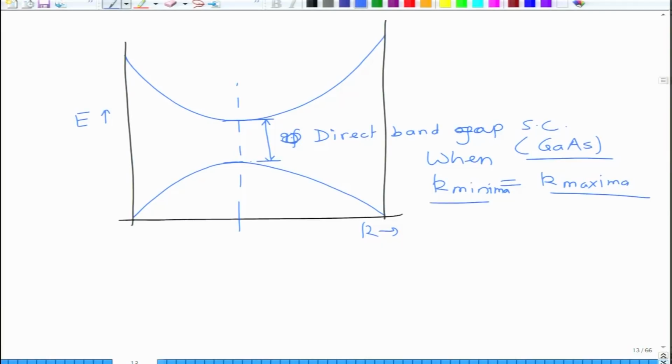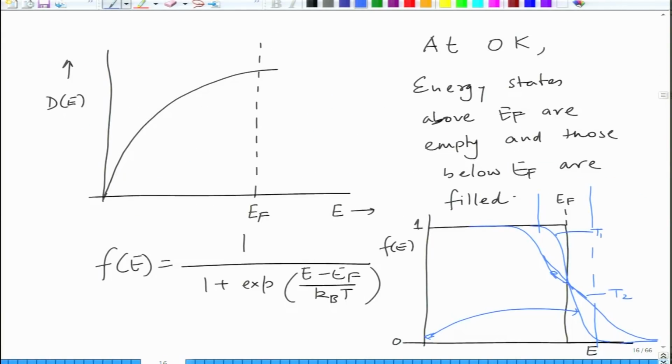Essentially, that is what we are saying in Fermi-Dirac statistics, that there is a reference energy Ef below which all the energy levels are filled. So, this valence band may be up to this part only, it may not coincide. It is just a hypothetical picture. When you provide some thermal energy, the electrons residing just in the vicinity of Ef get enough energy so that they can go to energy levels available above Ef. And then there are many empty states around Ef in which electrons can move around and conduct.